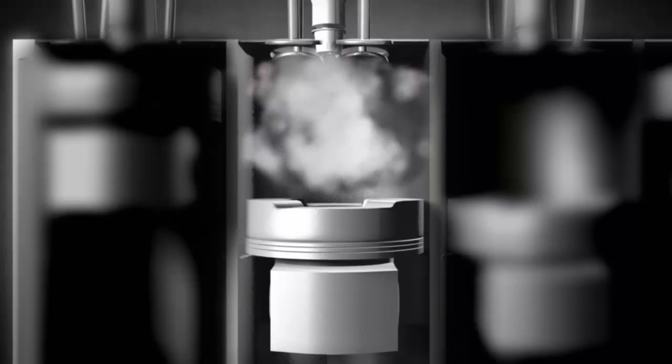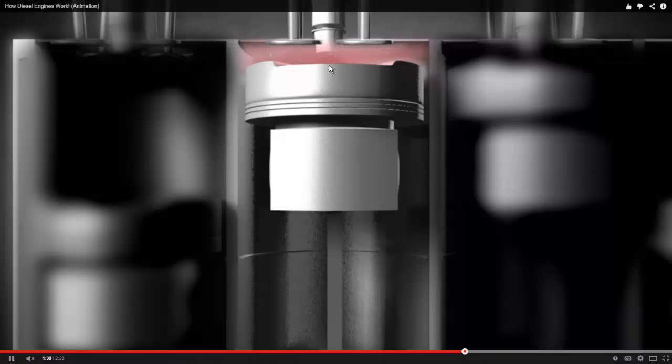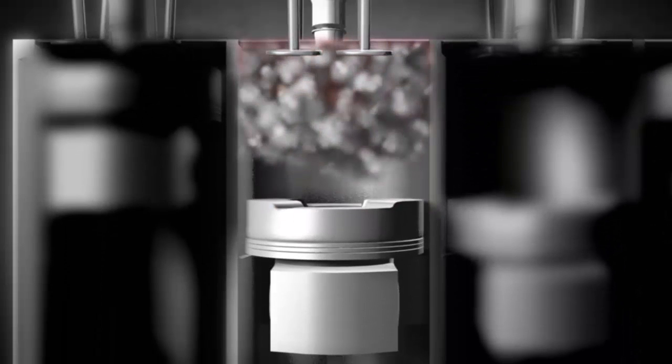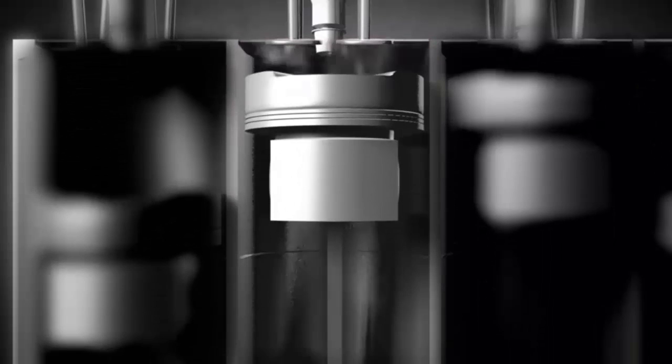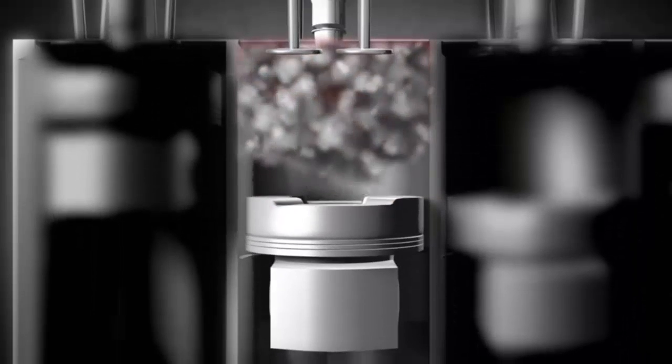This is the suction, the valves open and we admit air, then we compress it, we increase the temperature of that air, and in this injection we inject the diesel, and at the same time the diesel injected starts to burn, and that will create the expansion of that gas, and we have the power stroke. We're moving down. Then when we are at the bottom dead center, we open our valves, and then the piston will start moving up and exhausting. So let's repeat it again. Remember that induction is the same as suction for our description.